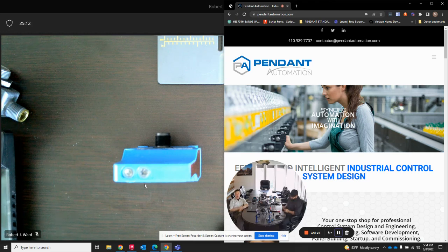Yep. So that's critical, and that's why, if I can do just a polarized retroreflective photo eye looking across the conveyor, I'm going to do it, because you end up with a solid line of coverage across the conveyor. All right.